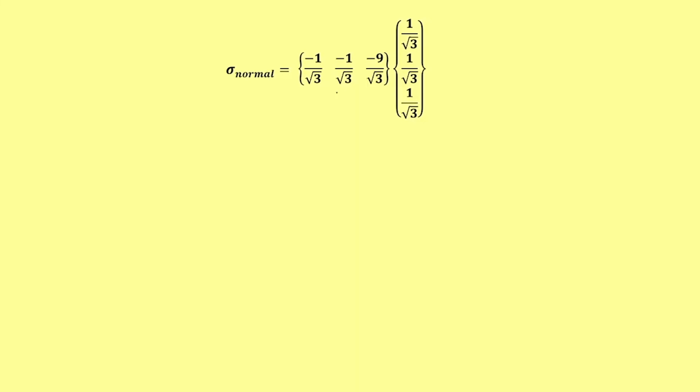That is what is done here, the traction vector T and the normal vector n. You do this simple matrix multiplication, and we get minus 11 by 3. That is nothing but minus 1, minus 2, minus 9, minus 11 by 3. So, the normal stress, or the normal component of the traction vector, is now known.